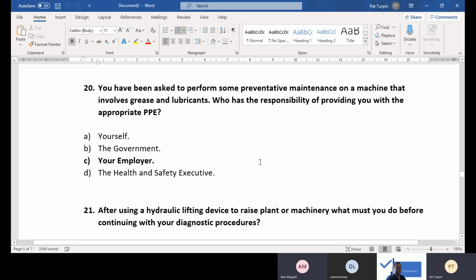Here's the right mask, check it. I worked with people, believe it or not, who were working with some nose bag masks. You know, the ones that cover your nose and have two big circles on the side? Absolutely brilliant they were. He was working away, grinding stuff. There was paint there, aluminium dust, paint dust, which is cancerous in that industry, all sorts of stuff. I walked up, watched him for a minute or two. I thought, he's got all his gear on, proper full goggles, his mask on, he's taped his sleeves up, everything. And then I looked and thought, he hasn't actually got any filters in it.